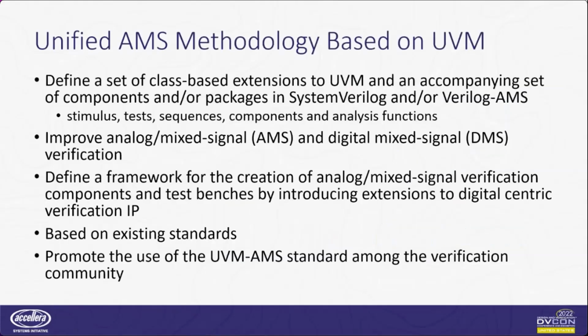So what we want to do here is start with UVM, which is a class-based library in SystemVerilog for digital verification, and extend as necessary that class-based approach for UVM and possibly create an accompanying set of additional components and or packages in SystemVerilog or Verilog-AMS to be able to produce stimulus, tests, sequences, components, and analysis functions for AMS and digital mixed signal designs and verification.